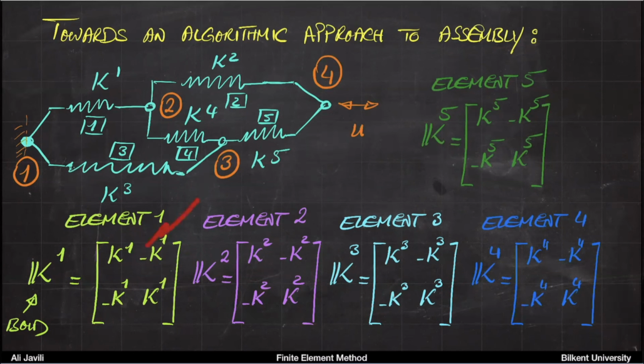So we go to element 1, we distribute its stiffness in the global stiffness. Then we go to element 2, then we distribute its stiffness into the global stiffness. Then we go to element 3, element 4, and element 5. So it's just like a loop over elements, and later that's the way we are going to write it in our programming. By having the corresponding numbers, it's very simple. You don't need any intelligence, and being able to do it without intelligence means that you can program it and your computer can do it, or your calculator can do it. And that's exactly the goal here.